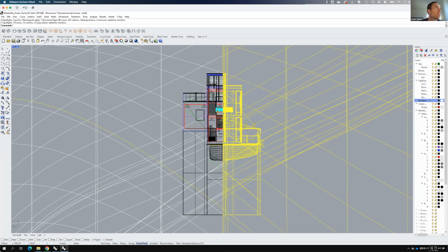And this is a very interesting material. It's not one that can exist in real life, but because we're working with V-Ray, we can create a very specialized material like this that is visually transparent, so we can't see it when we perform the rendering, but it's opaque to light. I call that type of material a see-through material.